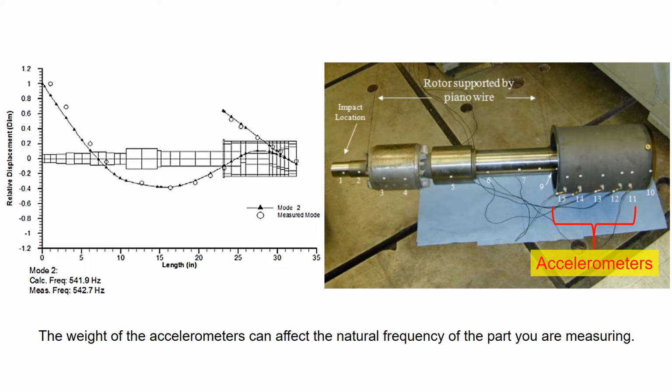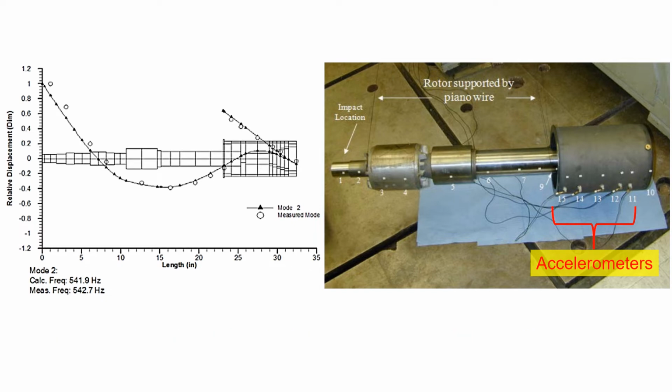But the weight of the accelerometer can affect the natural frequency of the part you are measuring. So if you are testing a light-weight small shaft, it is better to test with a small number of accelerometers that are also light-weight.